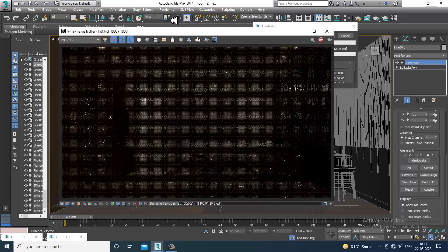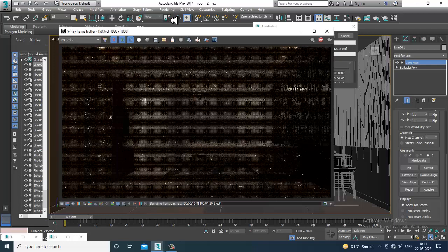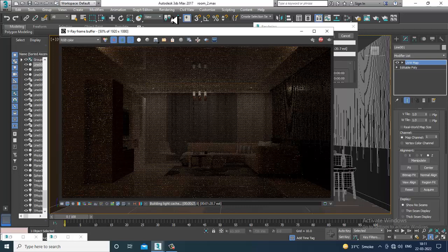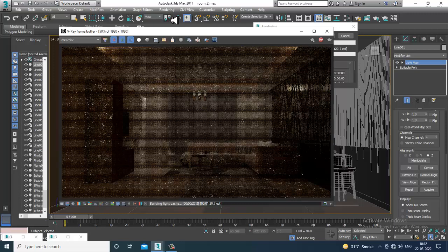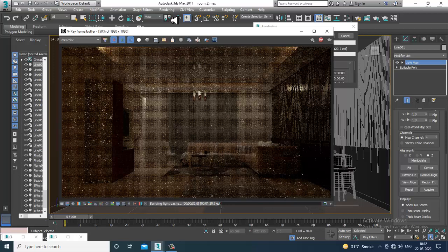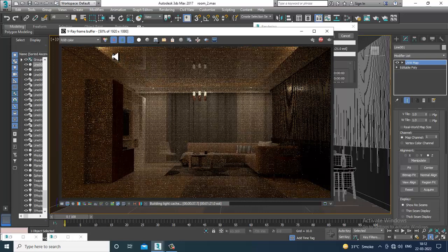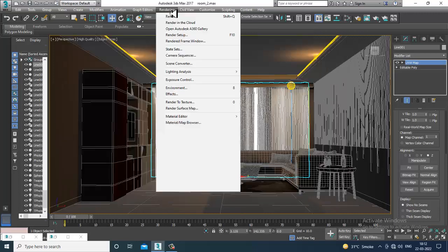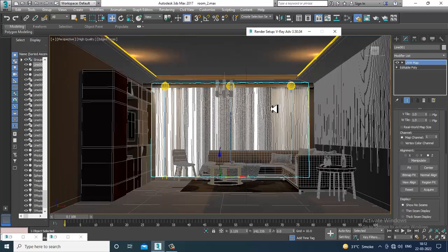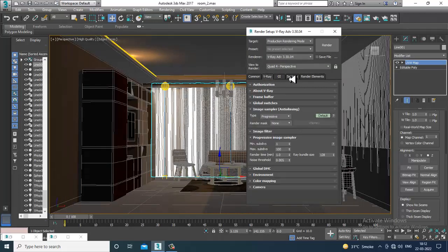We'll reduce the reflections which are there on the top. We can slightly reduce those reflections because it is very reflective. And if you want, you can reduce the intensity of these lights which are there on the top near the ceiling. Because I have not done any kind of render settings yet, we need to do that. Definitely will be doing it.